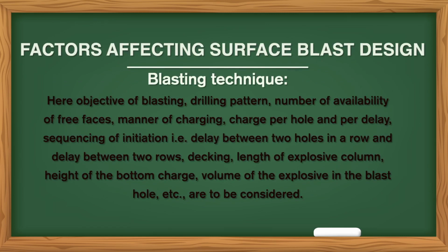Next, blasting techniques. Here, the objective of blasting, drilling pattern, number and availability of free faces, manner of charging, charge per hole and per delay, sequencing of initiation, delay between two holes in a row and delay between two rows, decking, length of explosive column, height of the bottom charge, volume of the explosive in the blast hole, etc., are to be considered.